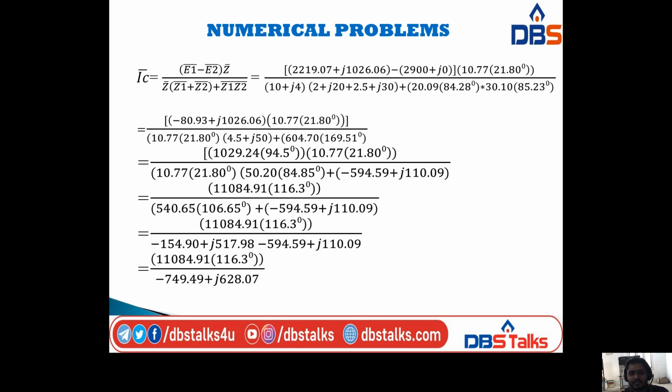20.09 into 30.10, that is 604.70 at an angle of 169.51 degrees. After simplifying the numerator we have 1029.24 at an angle of 94.5 into 10.77 at an angle of 21.80, divided by 10.77 at an angle of 21.80 into, after converting 4.5 plus J50 into polar form, 50.20 at an angle of 84.85, plus, after converting 604.70 at an angle of 169.51 degrees into rectangular form, minus 594.59 plus J110.09.